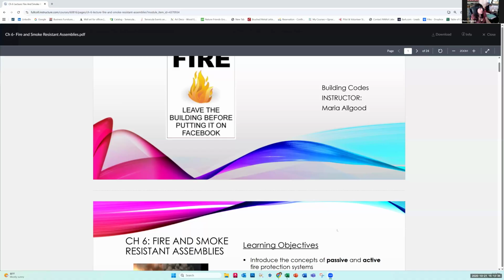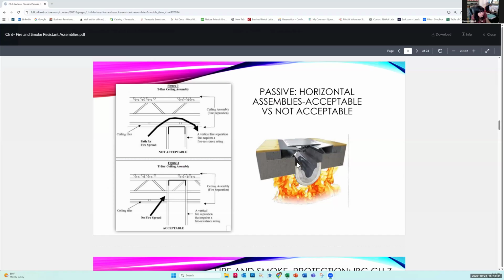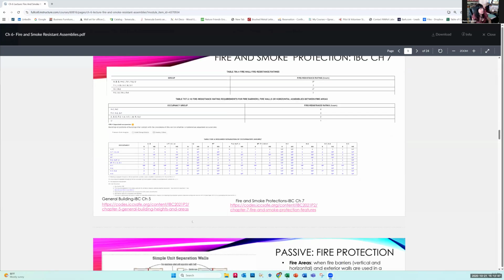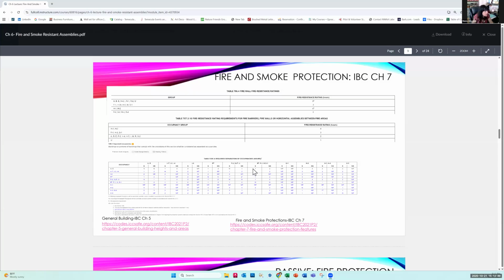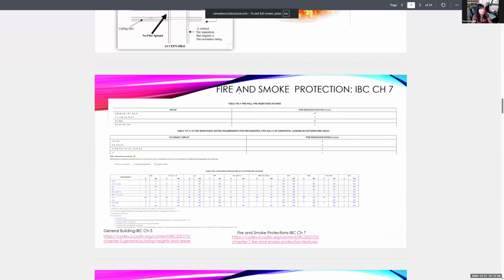Okay, so we are talking about these little penetrations, and you see right here, they're kind of talking about that ability. So where do you find all these little hour ratings? Right here. Let me make this a little bit bigger for you. In the NCIDQ, we can find what assembly has to be what hour protected rating. This is where we're going to find out what on our worksheet needs to be 1 hour, 2 hour, and so forth. They break things down by hazard, by assembly groups.